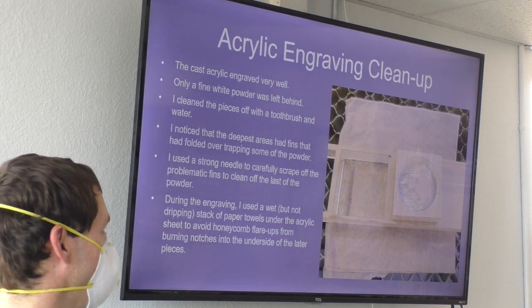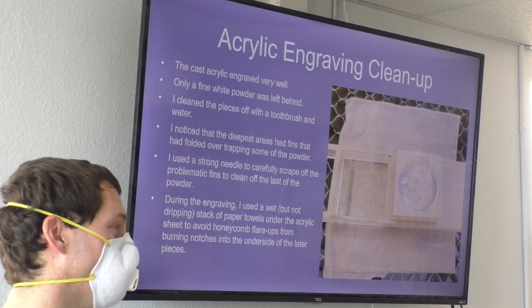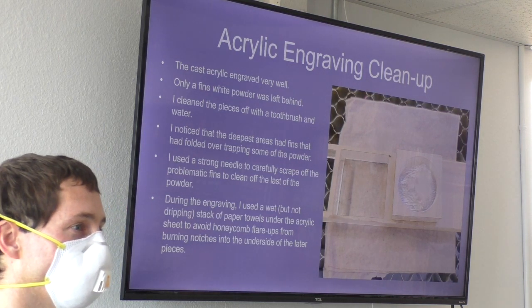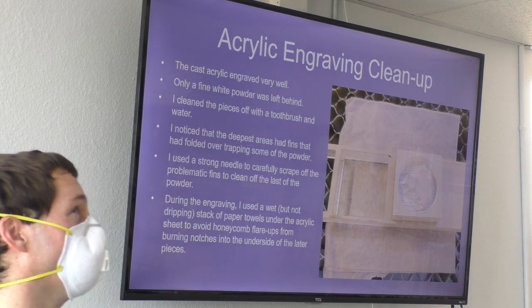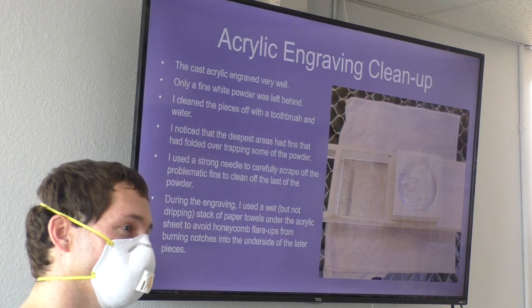And it's important that it not be dripping. You don't want to have water in the laser bed. You just want the paper towel to be wet itself. And you definitely don't want it to be a dry paper towel. That would catch on fire. That's a good tip. Yeah.